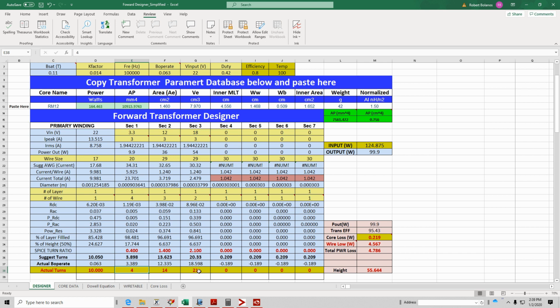And let me show you why I'm rounding it to 21, because if I set it to 20, if you notice right here, I will get 17.7 volts, and for this supply I need 18. So it's going to be a little lower. So if I go to 21, I get 18.5. Likewise, if I had lowered this to 13, I would not get 12 volts. Instead, I would get 11.4. So I can go ahead and set this to 12.